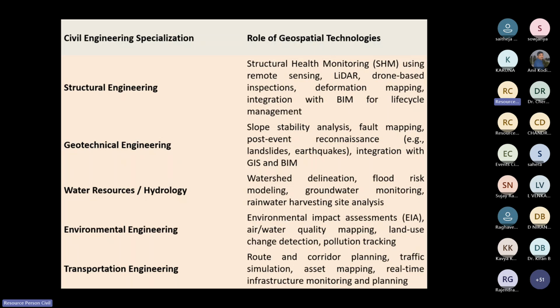With the water sample data like pH, EC, TDS, BOD, COD, and all these parameters, if you add them with the help of tools like the inverse distance weighting method, you can map the entire district. You can see how it varies spatially, how it changes from June to December, and how different parameters behave. You can also apply the same to soil parameters. So this is one of the useful tools for environmental as well as water resource applications.